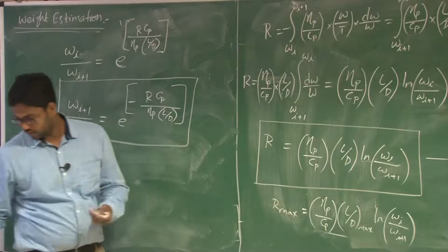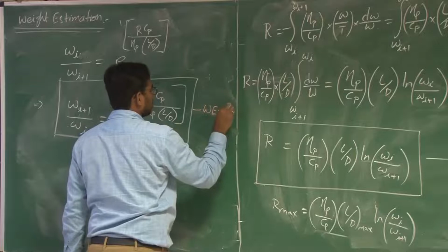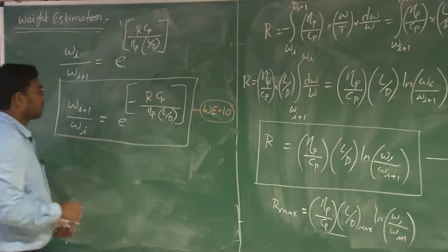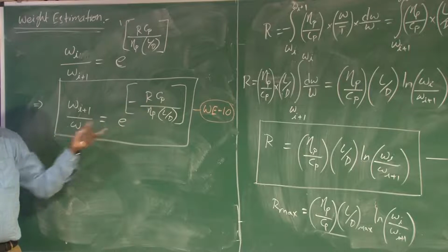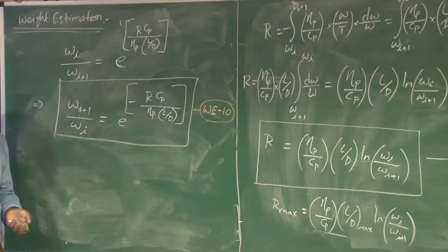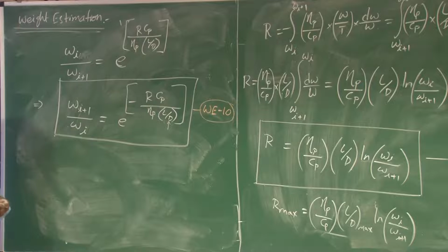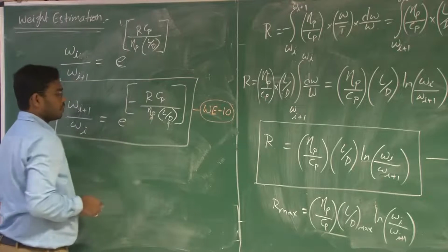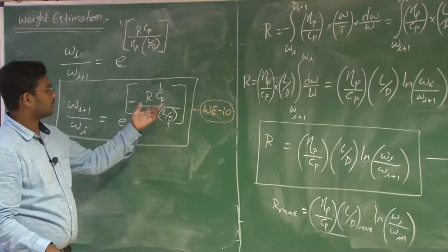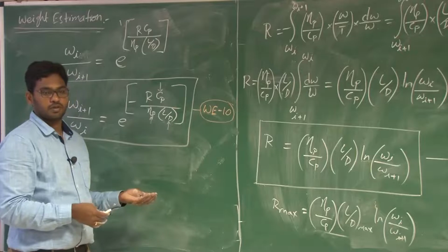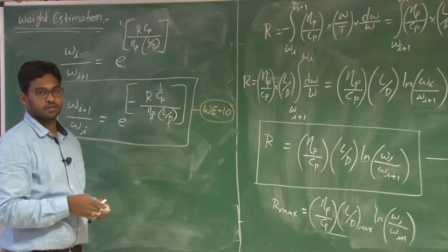So this is your weight estimation equation 10. If you want to have a range as per your mission requirement, you need to carry this much fuel load. The assumptions you have to make here are what the L by D of your flight is, and what the propeller efficiency can be, as well as from the historical data you will get to know the Cp of the engine used for this particular weight class of vehicles.